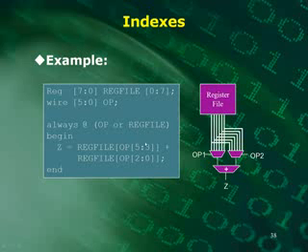So this value here, op[5:3], is going to go from 0 to 7, and that's what we want. We're picking a particular one, and then we're adding it to another one. The lower 3 bits of op can also be 0 to 7, so we're picking another location in reg_file, and then we're adding those 2 together. That's synthesizable. You can do things like that.